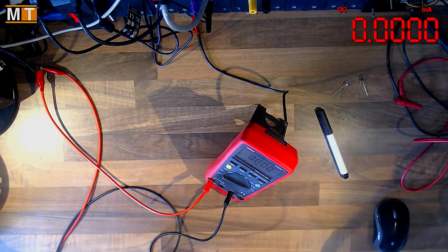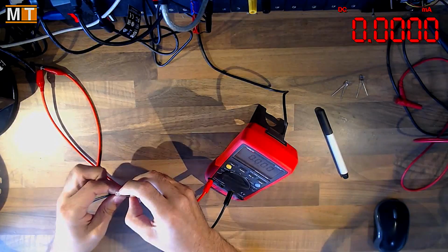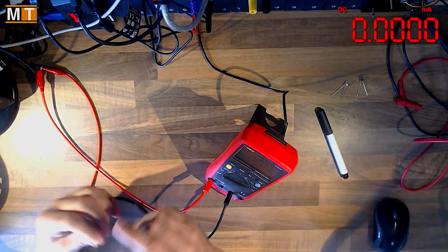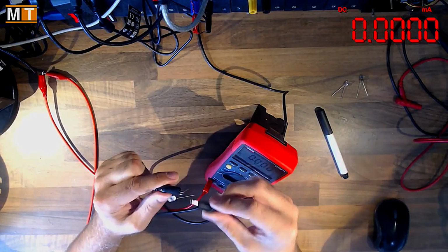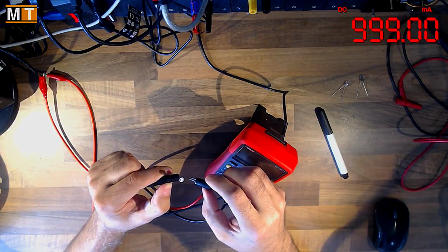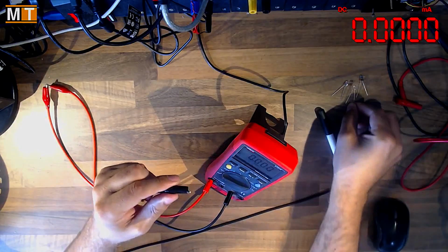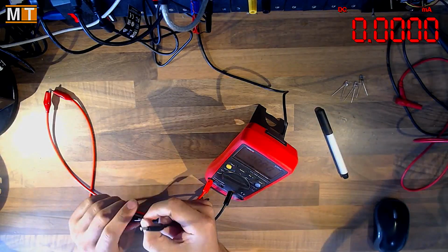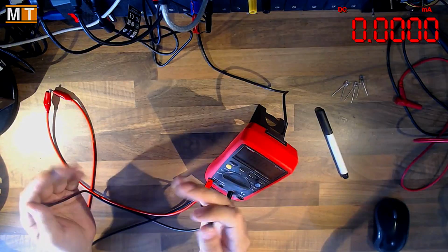Now, I didn't notice what the current was as it was going through there. That was limited to 1 amp, so it was probably going to be about 1 amp. So I'm going to do that again. That's fun. Don't want to hold the LED because that's going to get hot. Here we go. Yeah, 999 milliamps. Oh, that one blew a bit quicker. Nice one. Casualty number 3. So yes, without a resistor and with no limit on the current and the voltage not at the forward voltage, you get smokage.